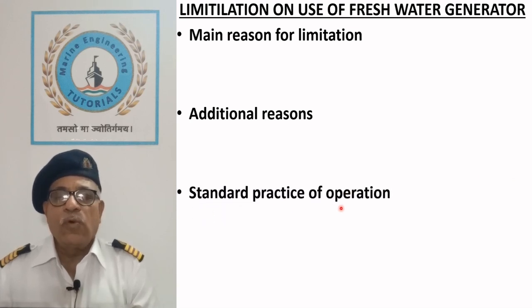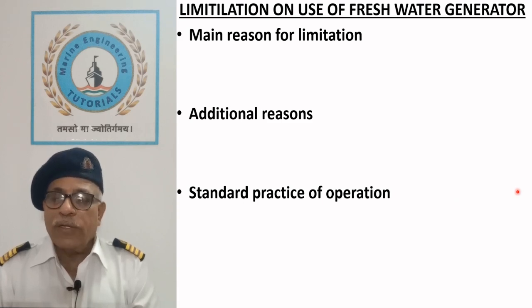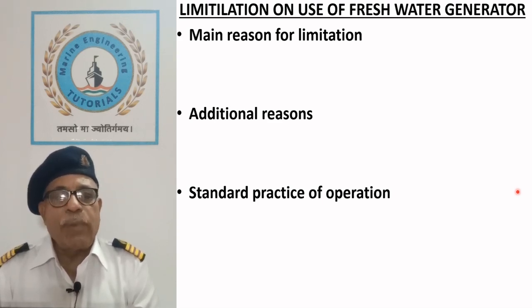Standard practice of operation. Thus, it is the standard practice to start freshwater generator when ship proceeds to sea after disembarking the pilot and is stopped at the end of the voyage before picking up the pilot.